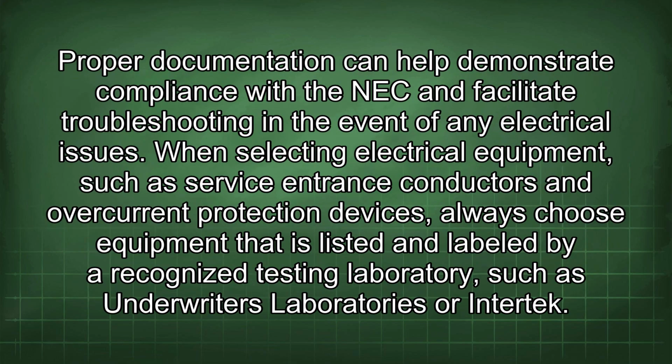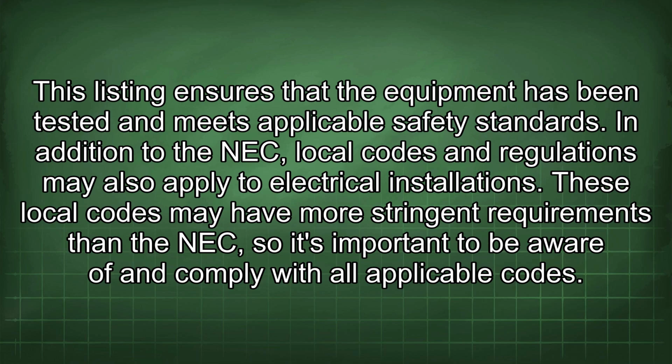Proper documentation can help demonstrate compliance with the NEC and facilitate troubleshooting in the event of any electrical issues. When selecting electrical equipment such as service entrance conductors and overcurrent protection devices, always choose equipment that is listed and labeled by a recognized testing laboratory, such as Underwriters Laboratories or Intertek. This listing ensures that the equipment has been tested and meets applicable safety standards.